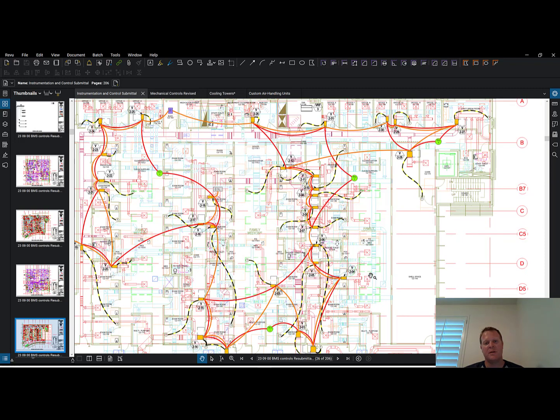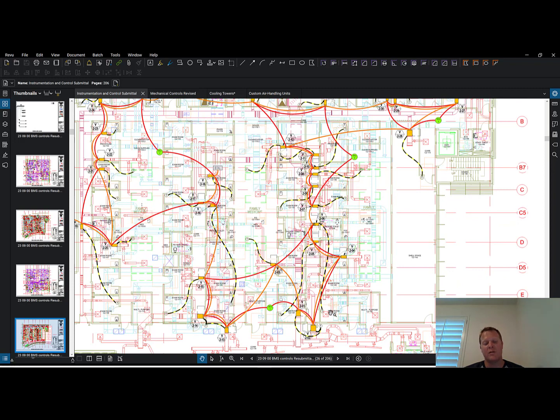Well, on a project like this, I'd probably make it all turnkey with the mechanical contractor. Mechanical contractor, you're going to provide all the ductwork, you're going to do all the low voltage wiring in your contract, and you're going to be responsible for all the controls. But that might not be the most cost effective way to do it. So we could send that out to bid different ways and say, okay, maybe our electrical contractor thinks he can do all the low voltage wiring, and we just need to hire a separate controls contractor to do that. Now, it can be done lots of different ways.